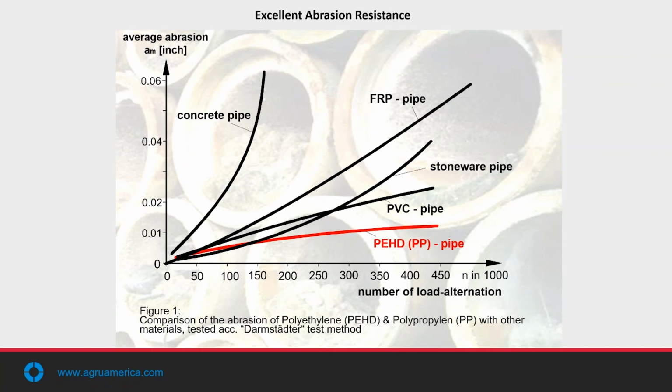So it's rotated back and forth, causing the material to transfer from one end of the trough to the other, back and forth. And in this graph, what we do is we measure along the y-axis the amount of material, or the wear of the material, that is lost. So the thickness of the concrete protective liner, or the thickness of the concrete, that is lost over a number of iterations where that material is sloshed back and forth.